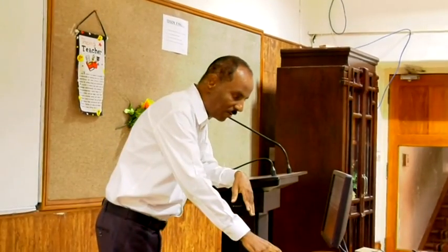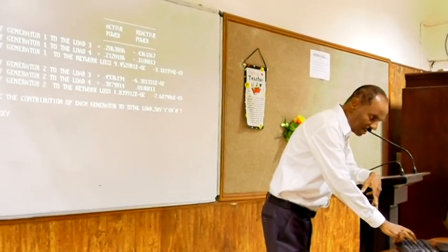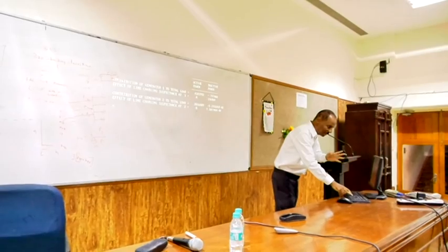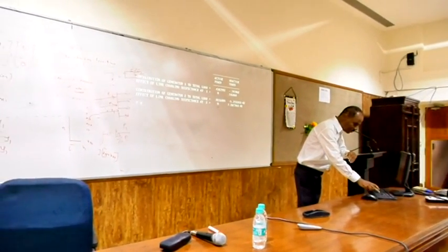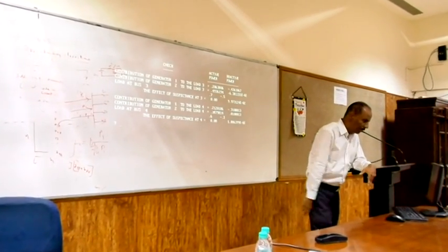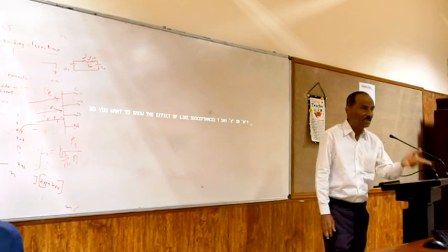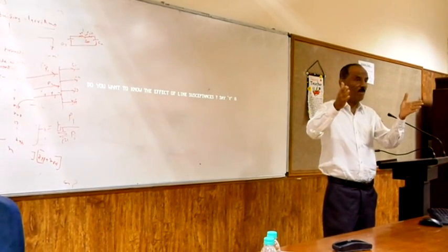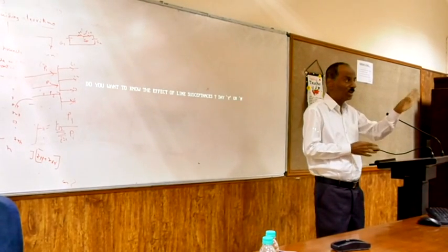A circuit is also given. Again you can say the same thing, all available in the file which you mentioned now. Similarly, you can split up, everything is given. You can use this software for finding the sharing of all the active power. Similarly, the susceptance contribution can also be calculated, because in each line we have half line charging susceptances. The effect it will also give.